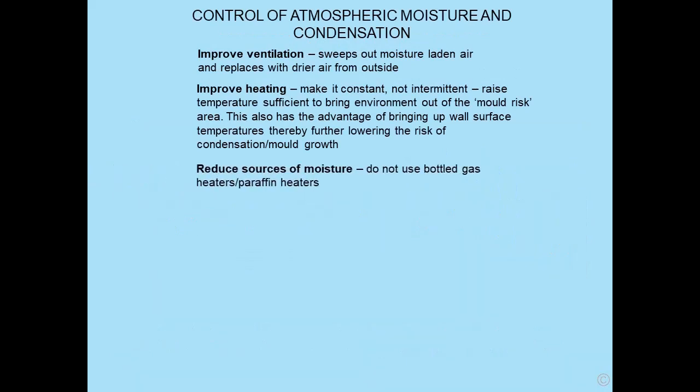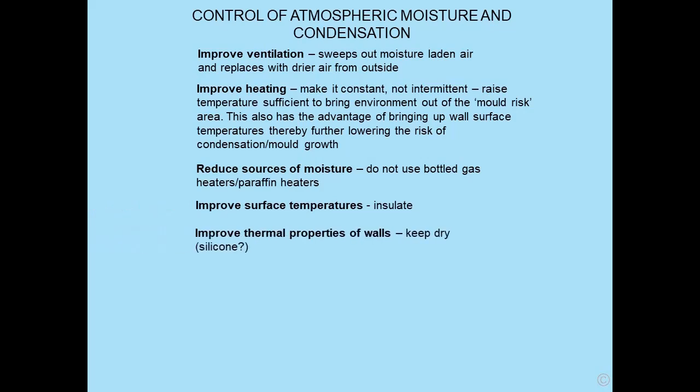Reduce sources of moisture. Do not use bottle gas heaters or paraffin heaters. Apparently, large dogs give off as much water vapour, if not more water vapour, than a large human. Improve surface temperatures. We could use insulation. Improve the thermal properties of wall.